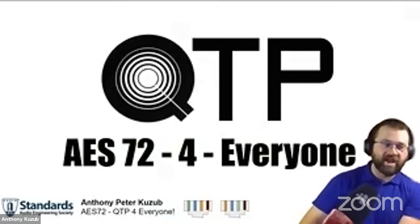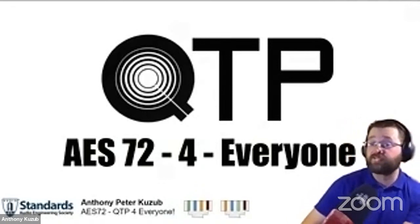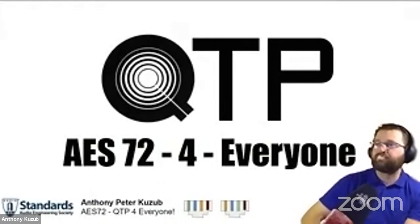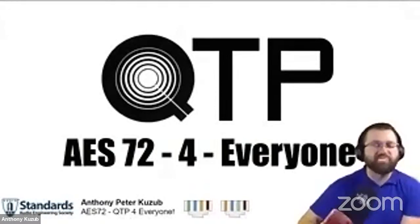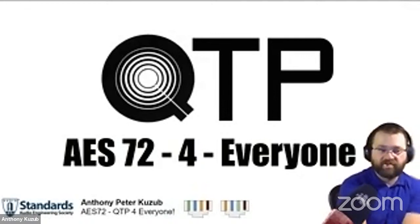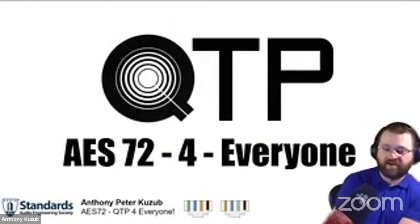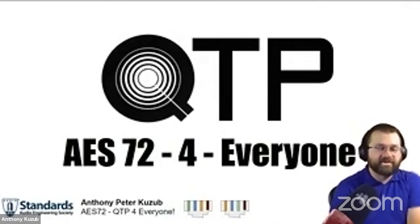And again, we're not there yet to say this is the way to do it, because we don't have that much data on it yet. But there's so many systems and patch bays throughout the world. It's impossible to ensure that shield connection is there throughout the whole thing. Again, some of these things, it's a common return path to ground. Phantom power and microphones. These are problems that plague us.